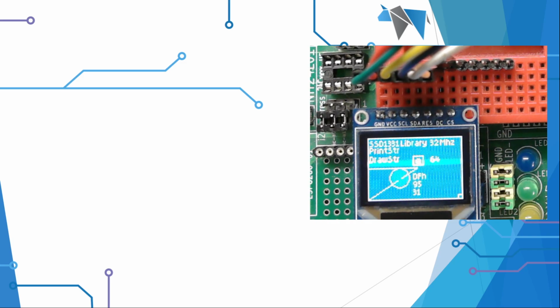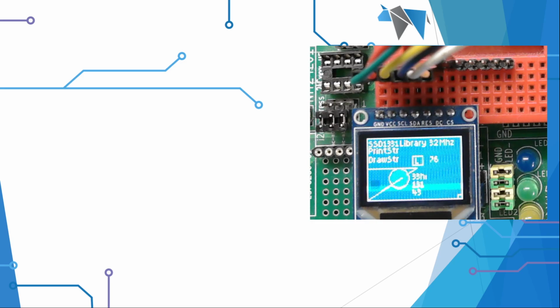And you can see it is faster. But this proves to you that the SPI library is working. Therefore, the clock line is working, the data line is working, the reset, chip select, and the data control line are all working because it's working in both software mode and in hardware mode. Any good library would support both. You just need a constant to change. Okay, that will do.